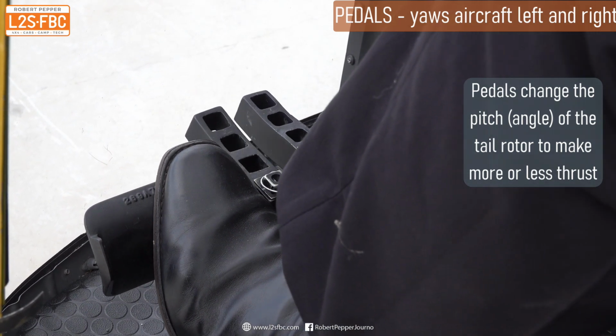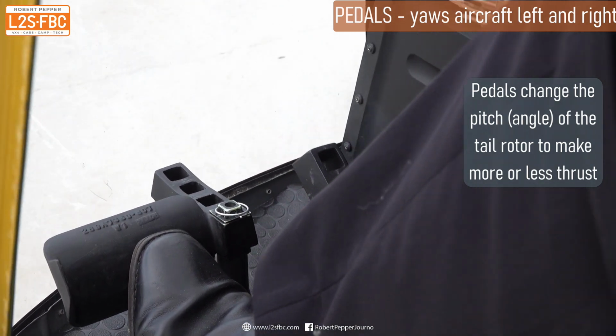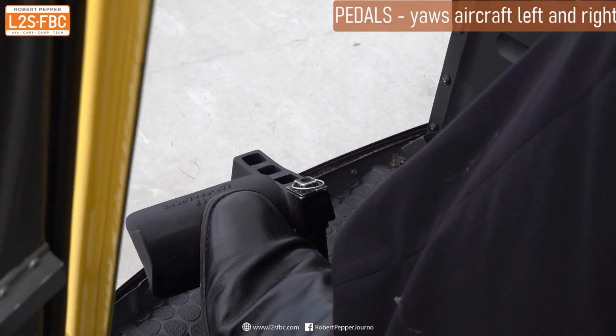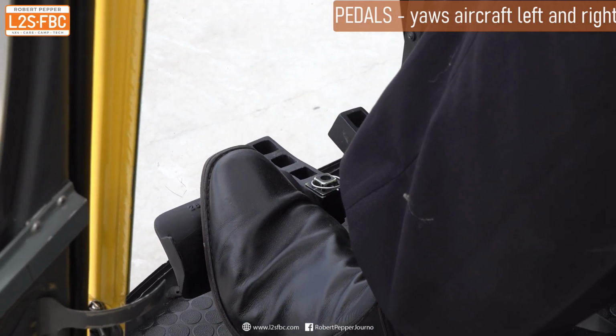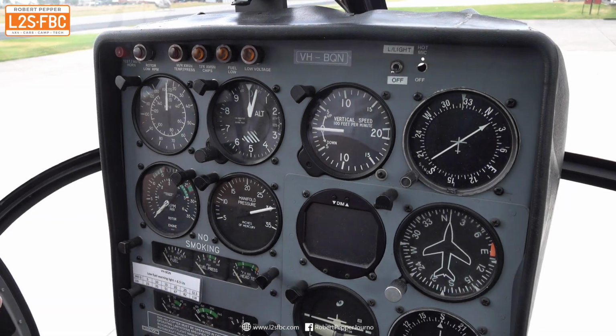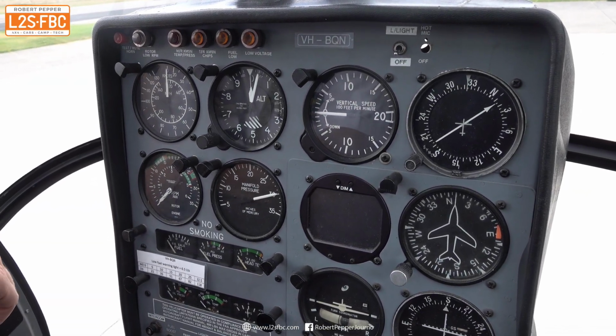I'm going to swap legs now, and left pedal comes forward, and the nose will yaw to the left. It's a very sensitive control, and as such you only need a little bit at a time to correct the yaw.